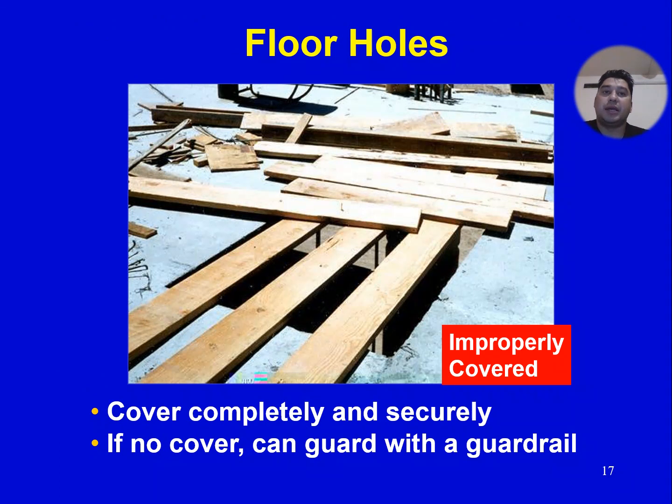Now, floor holes. Cover completely and securely. If there is no cover, guard with a guardrail. You can see here it is not covered properly. People's legs can fall in and they can get injured, and even the people can fall in. So any hole should be covered properly and completely, not half covered and half left open. It should not happen like that.